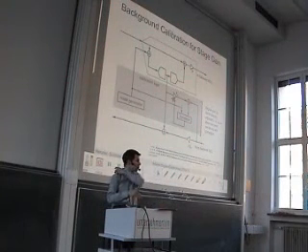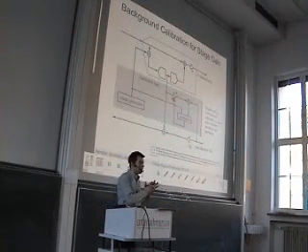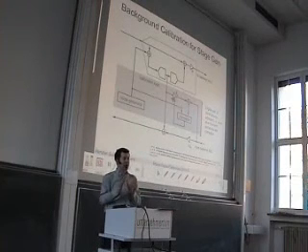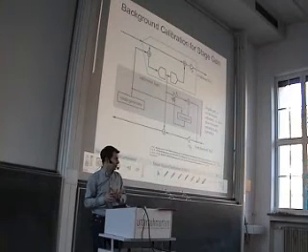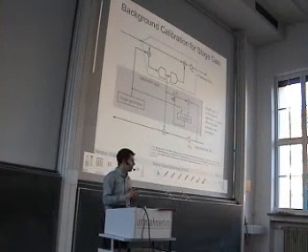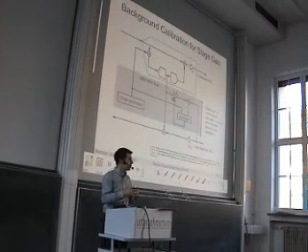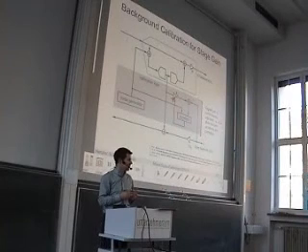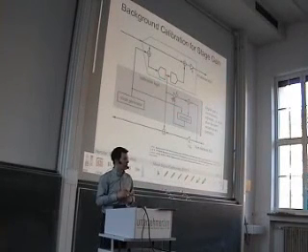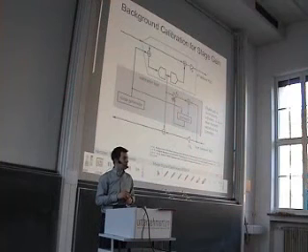Well, what you can see here is that the circuits become quite complex and complicated if you want to go robust. So we started with this very basic algorithm, which was a binary search. Then we saw that we can run into problems if we have variations. We found a countermeasure, which requires a much more difficult digital post-processing. And then we saw that there is a matching requirement, and this matching requirement for very precise converters also requires a calibration.